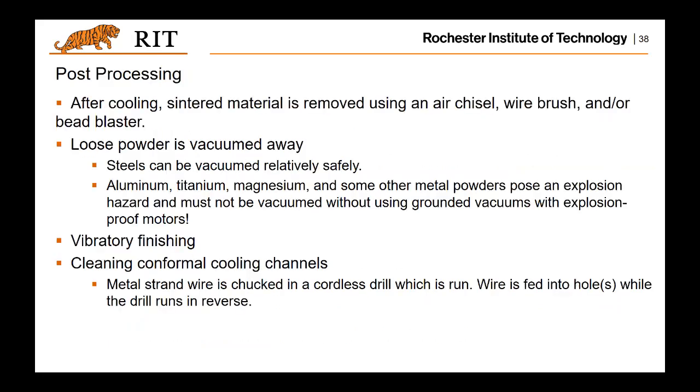So post-processing is also critical for EBM printing. First things first is to remove the sintered material. What you could do is a vacuum process to remove the loose powder.